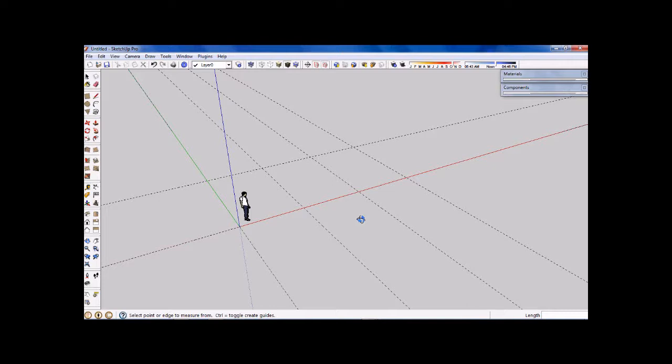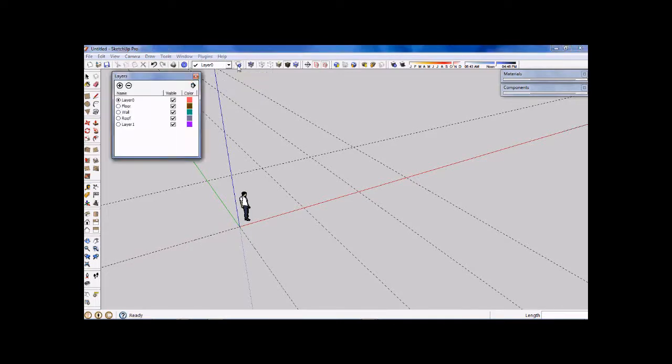Let's all try this for the moment and we'll come back again. Go up to your Layer Dialogues Manager button beside the drop down text box, click on it and change your current layer now to floor. You change your current layer in this dialog box by changing the radio button up the left there, clicking in there, so that now floor has got the solid dot next to it. That means it is the current layer.